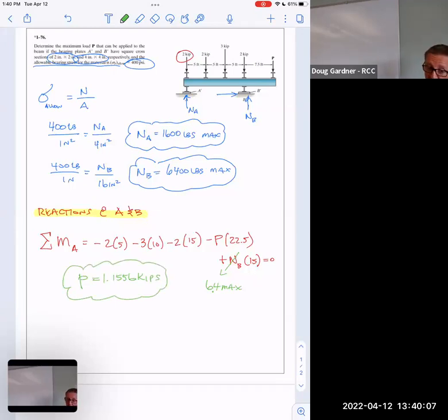So if I go over that, then that means that 6.4 is going to go over. Notice there's no factor of safety on this. But if that was calculated with a certain factor of safety, like if this was a 1.2, again, you won't see this in your assignment, but if this was supposed to be a 1.2 factor of safety, then I would take this number right here and multiply it by 1.2 and just make it bigger.